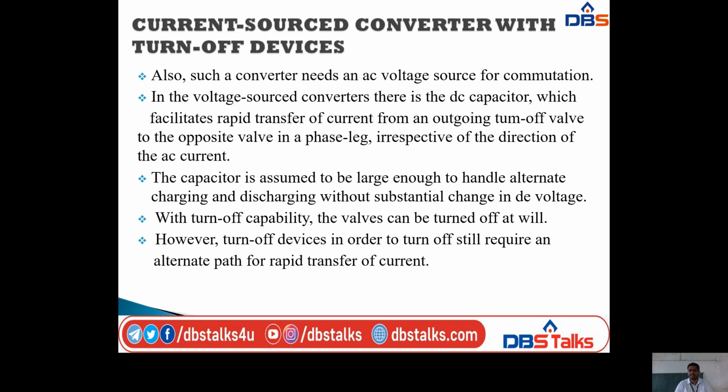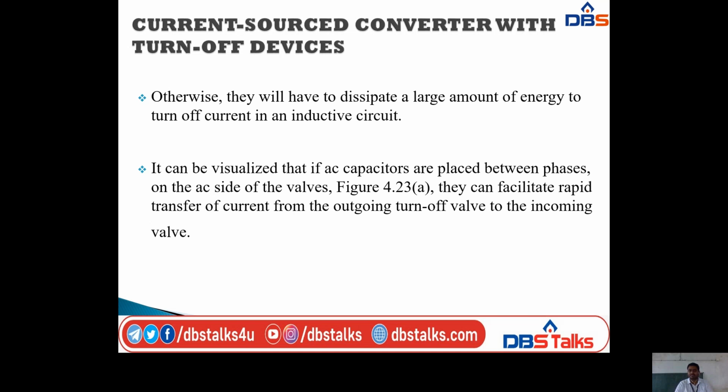However, turn-off devices, in order to turn off, still require an alternate path for rapid transfer of current. Otherwise they will have to dissipate a large amount of energy to turn off the current in an inductive circuit.